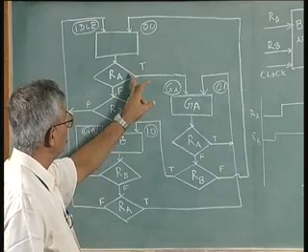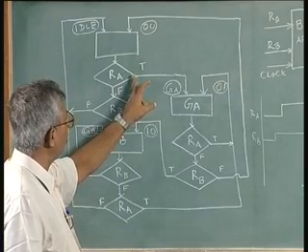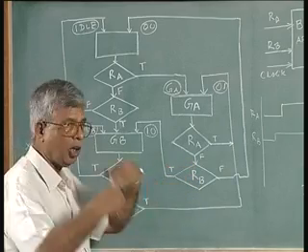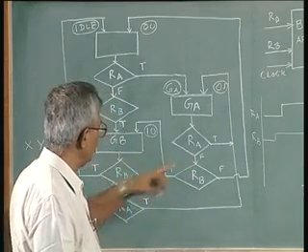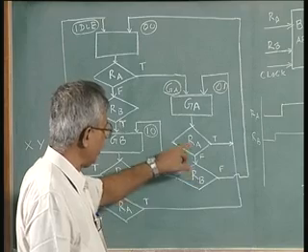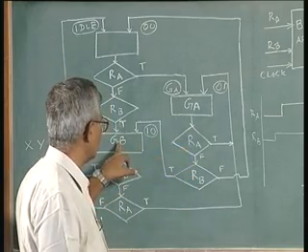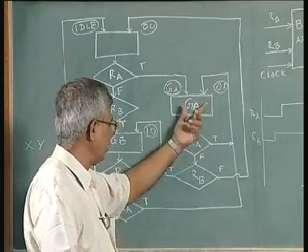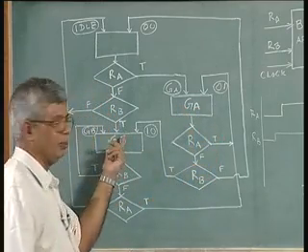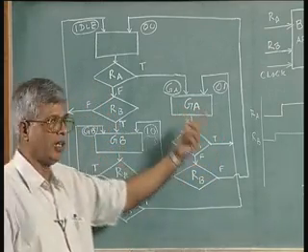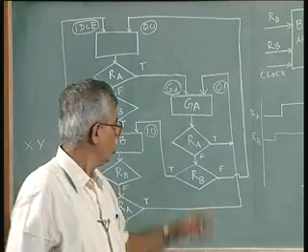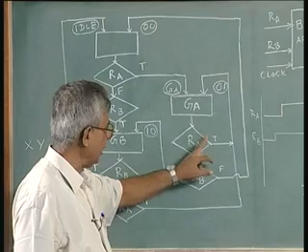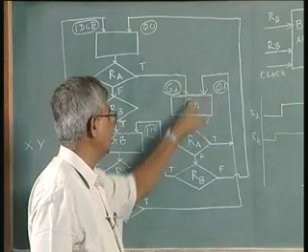Now, in this case I will put the problem in a slightly different way. Supposing RB is also true. RA will be given and then you will find RB true, so it will start giving GB. So, GA is not completed. There is only one clock period for GA, and in the second clock period GB will be available. That is wrong. I want GA for as long as RA is available. So, if I do not check this, only when RA is removed completely, as long as it is true, I will have to keep circulating this loop.